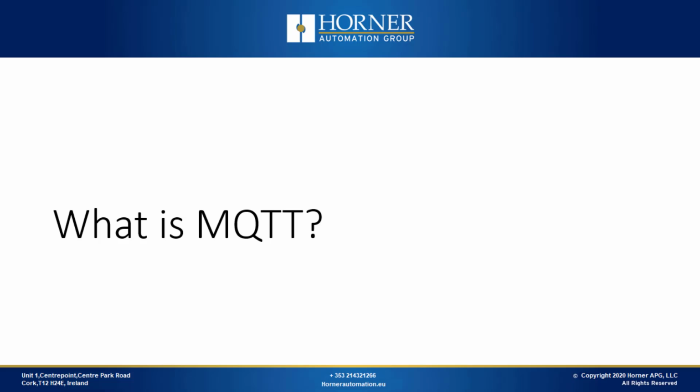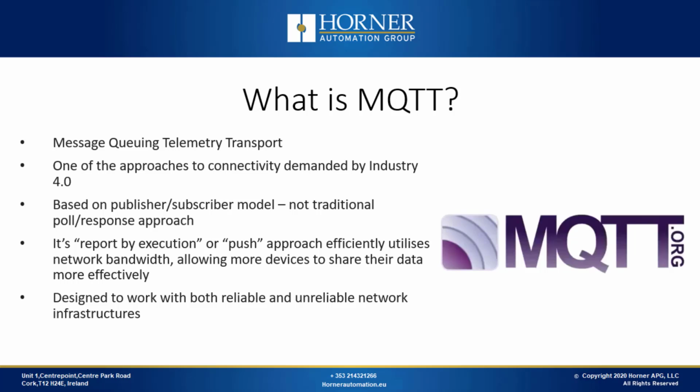Now we're going to talk about what MQTT is and how we're applying it. MQTT stands for Message Queuing Telemetry Transport, and it is one of the new approaches to connectivity demanded with the increase of machines coming online, reporting more data. It is based on the publisher-subscriber model and not a traditional poll response approach.